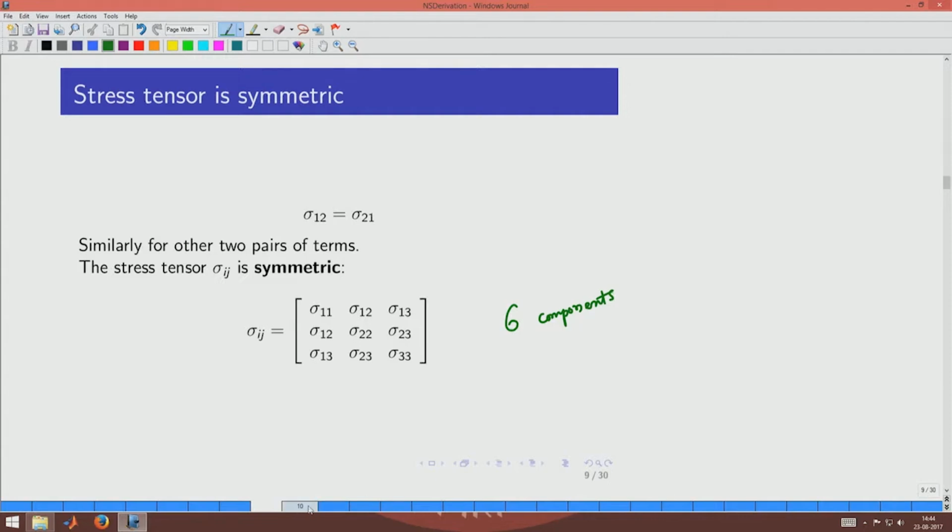Now, here is where we see the sense of sigma and sense of pressure. So, let us consider sigma 1 1. Okay. So, what does sigma 1 1 mean? If you take x1 and x2 directions, it means the force acting on a plane x1 in the one direction, okay, on this plane, force acting in this same x direction, which means that it is basically the opposite of pressure, because pressure is trying to compress this body.